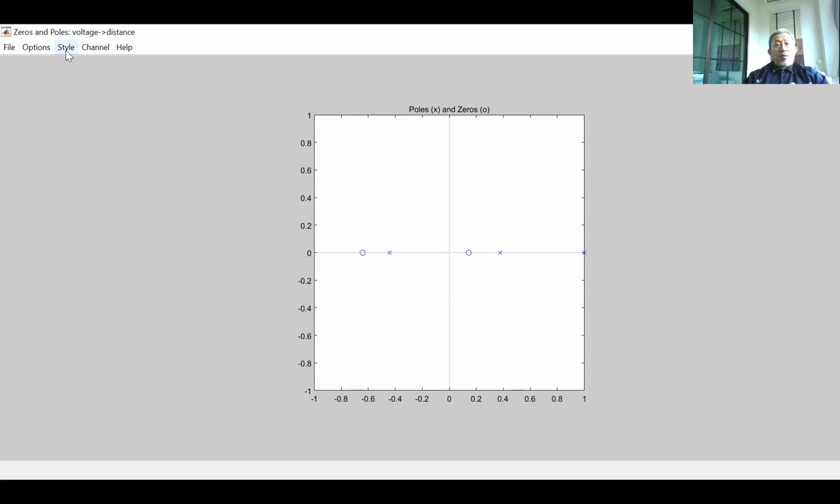Your unit circle is shown here with 3 poles inside the unit circle, system stable. The status now changed from non-minimum phase to minimum phase with a high sampling frequency at 55 milliseconds.